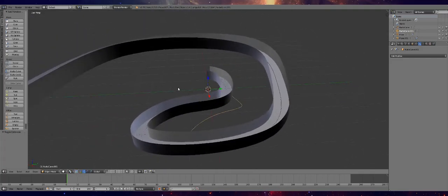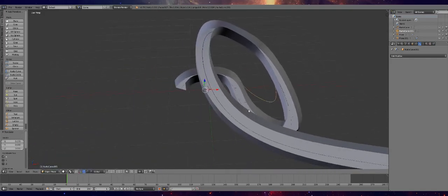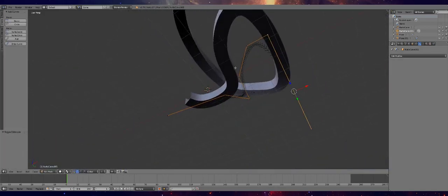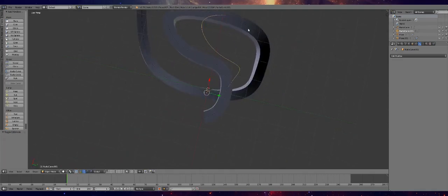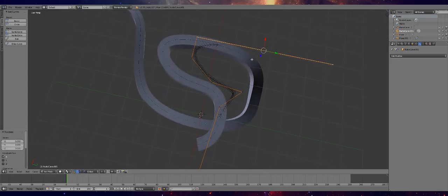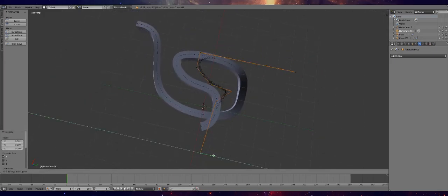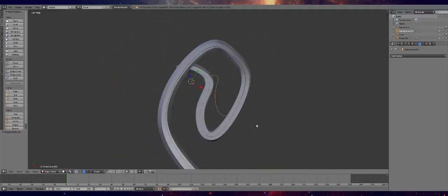If you just look at it, this is not the best. Maybe if I move it a little bit more like this. Yeah, let's take that. You can see here this last part never quite meets the center. You want to center that preview line, that spine, on the center of the track. You can see now I have it a little bit offset, so I fix that. Hey, that's way better. This one is also a little bit offset. It's just there. Now this is a good spline, not design wise, but talking about the basics of Blender.